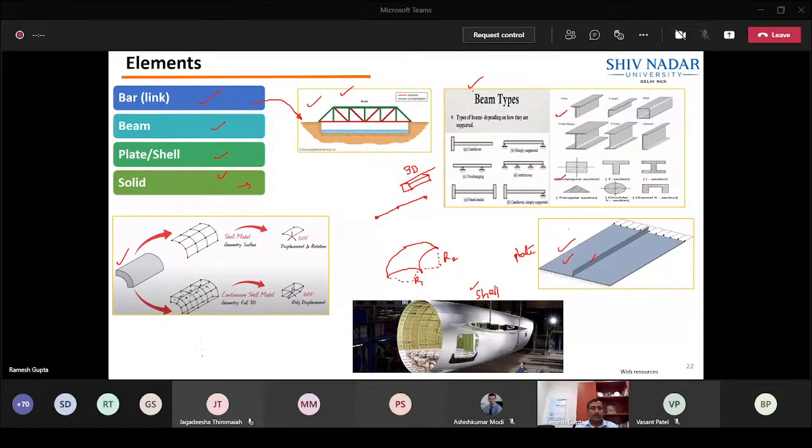Now, if you carefully observe, in actual practice, let's say this is a 3-dimensional object, think of it as a cylinder. I can take the reference surface in the form of 2D and model it as a shell element. Now, if I take one element out of it, you can look at each node and find the degrees of freedom. So if I write the hierarchy, one is the element, then nodes, then degrees of freedom.